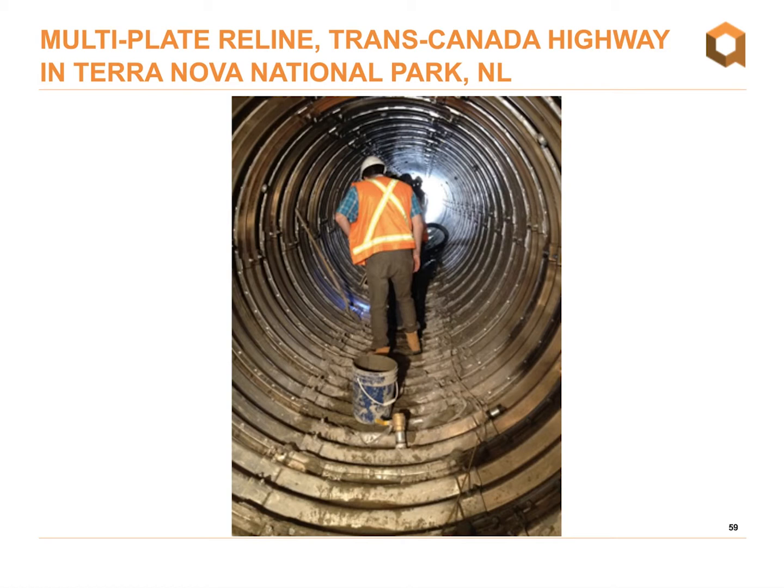Each ring was bolted to the previous ring through an inward projecting vertical flange. This allowed the assembly, of course, to be completed completely inside the host pipe. And after only 3 days, the crew of 3 were able to complete 20 rings in a day.